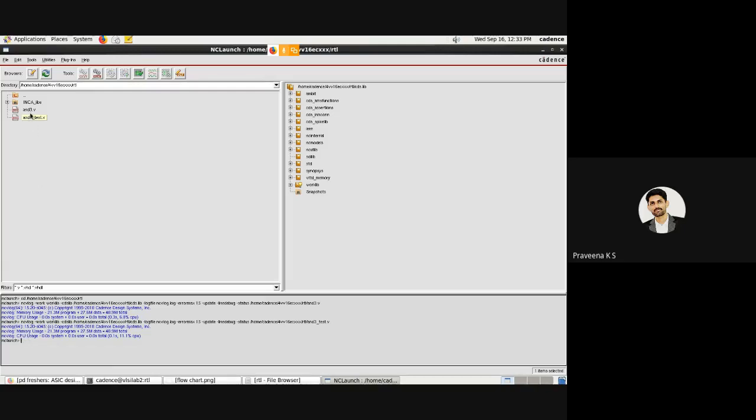Now, once we check for errors, it will create its hardware codes or structures in the worklib folder. On the right side, there is a folder called worklib. Inside that, it will create two modules, and3 as well as and3_test. This one is for the Verilog code and this is for the test bench. Now select and3 and come back here.